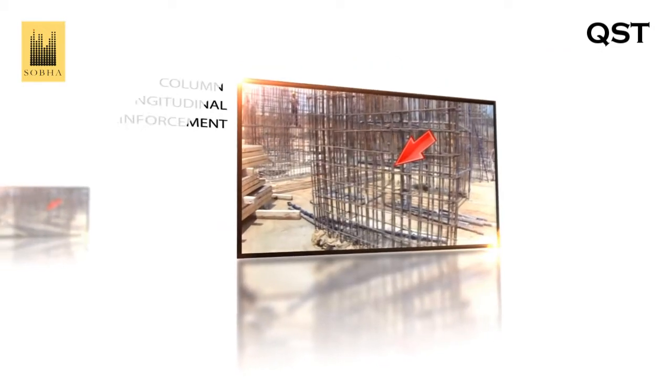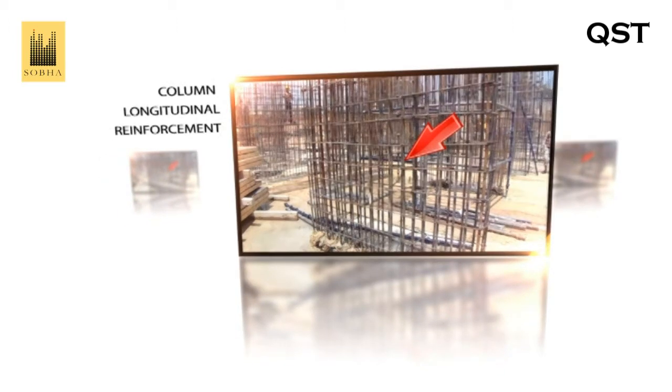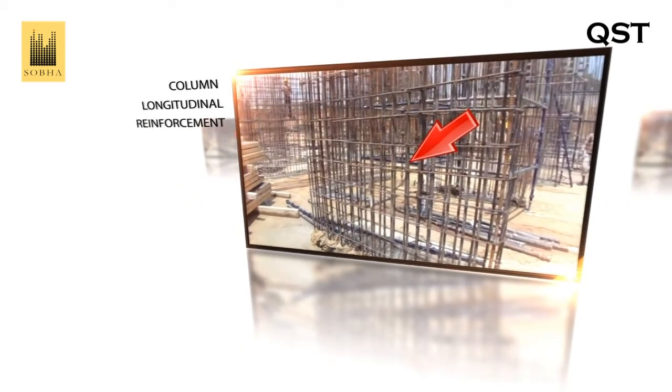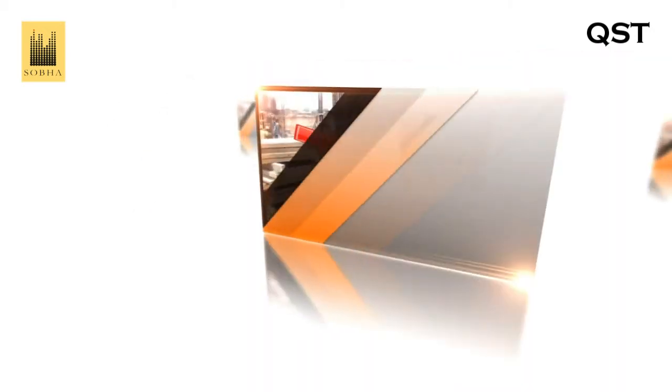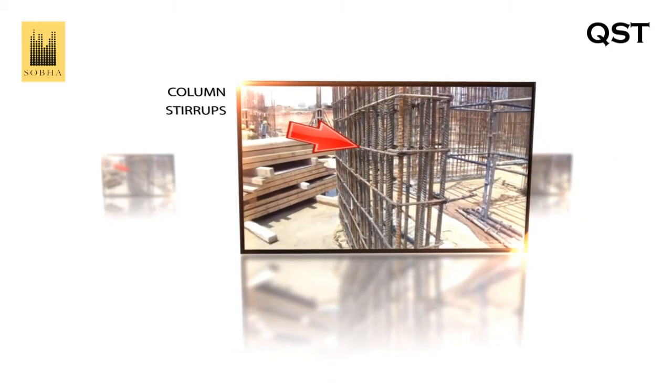Column reinforcement. Longitudinal bars and transverse bars, which are nothing but stirrups. Column lapping are the sequence of work in column reinforcement. The column bars need to be supported from all four sides using props and the verticality of the column to be checked. Stirrup spacing, hooks and links, number of rods, dia of rods should be as per good for construction drawing.